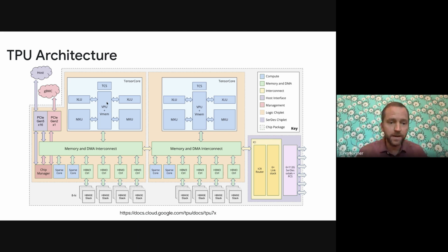The other piece here is the VPU, Vector Processing Unit, and that is responsible for doing essentially the stuff that's not linear matrix operations. So this does the nonlinear work and exponentiation and sine waves and all those sorts of types of calculations. And also the virtual memory is sitting right here on the die as well. So the VPU can also do things to memory to help set it up for the MXU. These are little logistics chips that are shown here on the top.